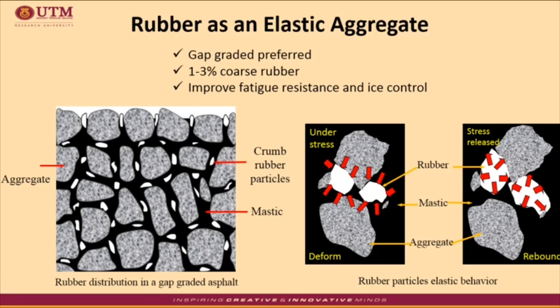The theory discussed above was applied in the production of a mixture with enhanced elastic recovery properties under repeated loading. This enhanced the mixture's resistance against fatigue cracking. Previously, laboratory tests indicated major increases in fatigue life and crack reflection control due to increased pavement flexibility.